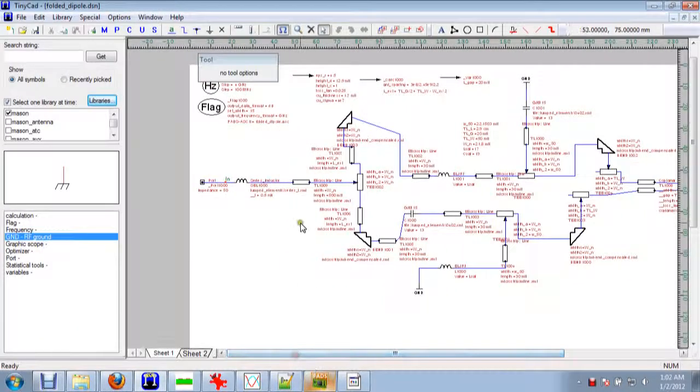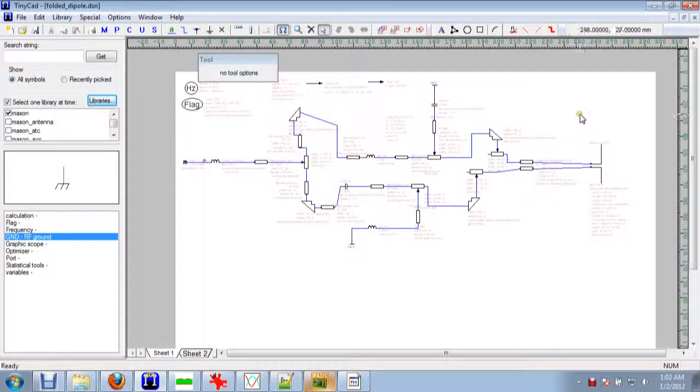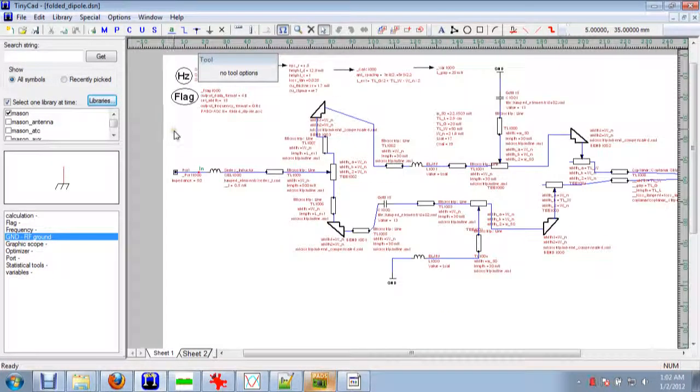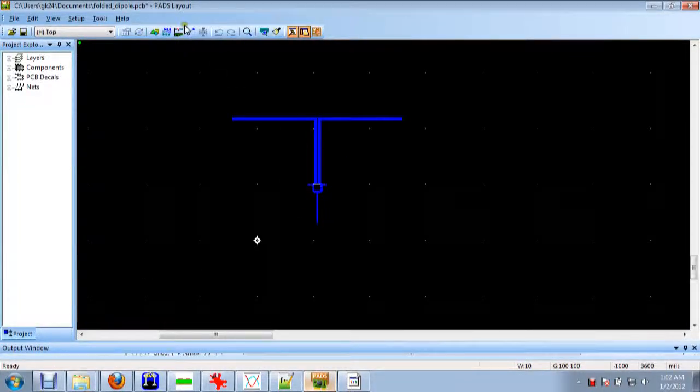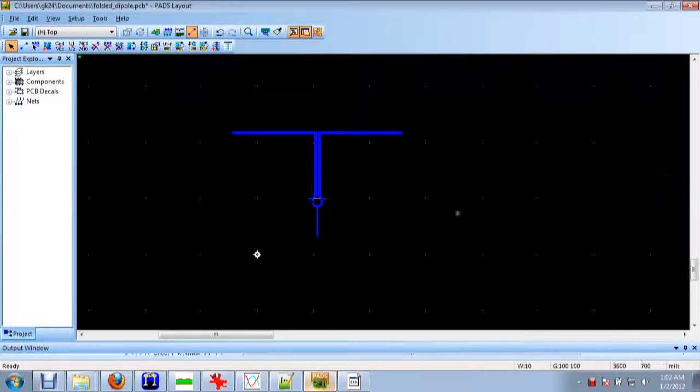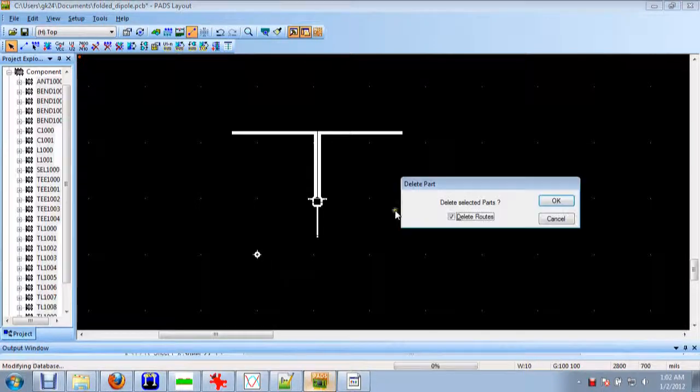But really, if you want to attach something like this into a schematic, what you really would like to do is have your DX Designer have a schematic part for this structure, and you would want to be able to reference just a single item.